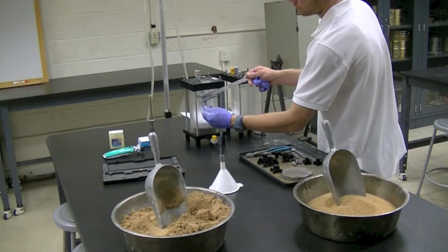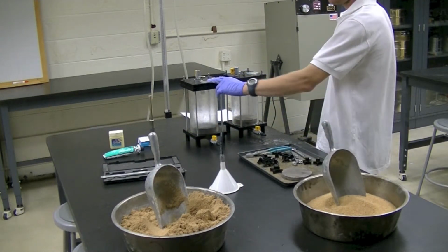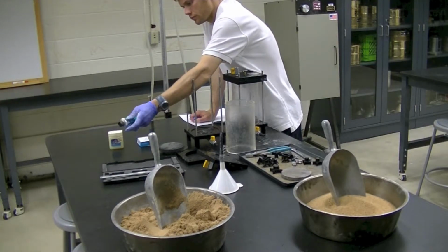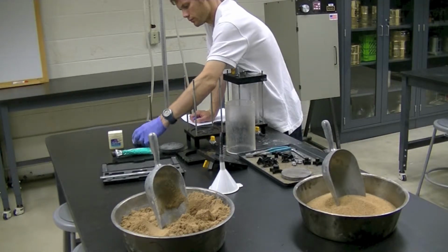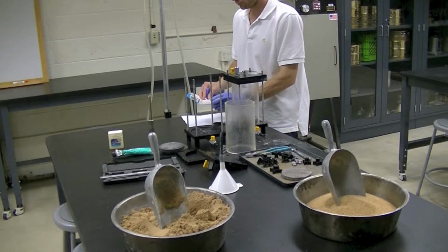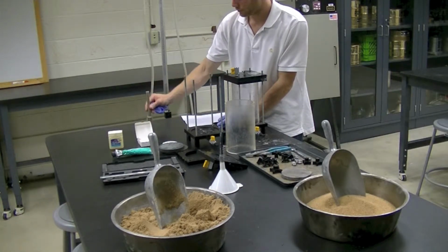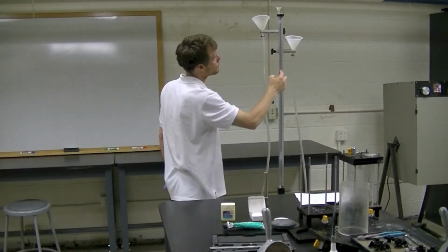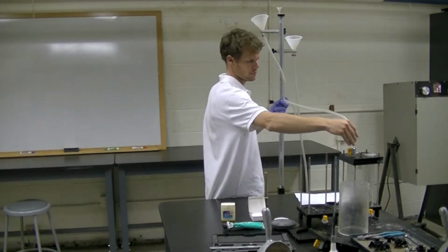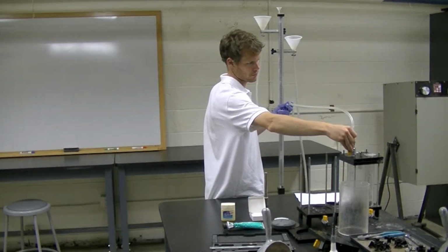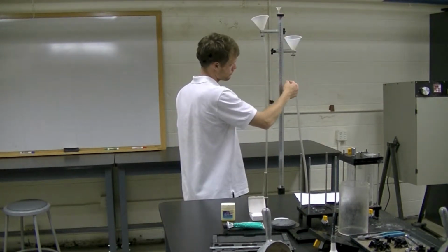We have a caliper to take inner diameter measurements of the permeameter as well as length of the specimen. We have our permeameters, our vacuum seal grease to ensure water tightness, our Vaseline, and filter papers. We use the filter papers to cover the porous stone to keep it clean and free from aggregate. We have our tamper. We have our assembly for falling head and constant head. Here the tubes are used for constant head tests and attach into the top of the permeameter. That middle tube assembly is for the falling head test.